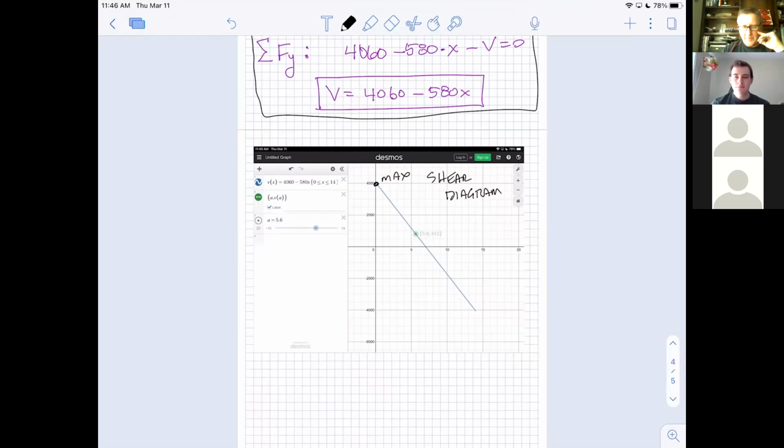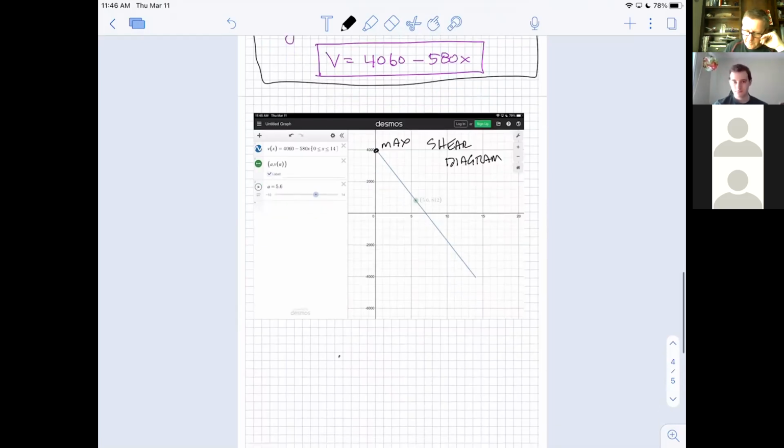Does it also make sense, because there's not much shear in the middle, that if there was such a thing as a beam that was actually built like this, that beam would structurally hold up? It's just that it costs more money to cut a beam like that than it does just to cut the entire beam. But it basically is telling us the middle of this beam doesn't really matter that much. As a matter of fact, we could even skinny it down to almost nothing, like make a bow tie out of it, and it would actually do the job, because more and more shear strength is required as you get to the ends. So really thick on the ends and really thin in the middle would actually work, wouldn't it?